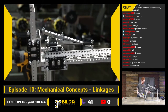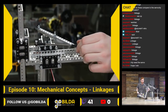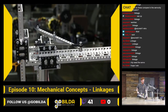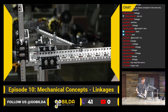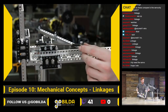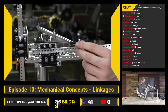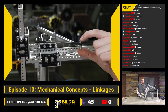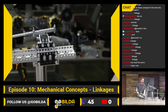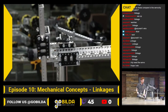The second bar in this case is a linkage set. It is a ball end joint with some threaded rod, some M4 threaded rod. These are really nice because you can really tighten down on the screws in this assembly, and the actual part will rotate on the ball bearing, or the ball, excuse me, without rotating around the screw, which means that system can stay pretty darn tight. Whereas if I had used two beams there, I might not have quite as much rigidity.